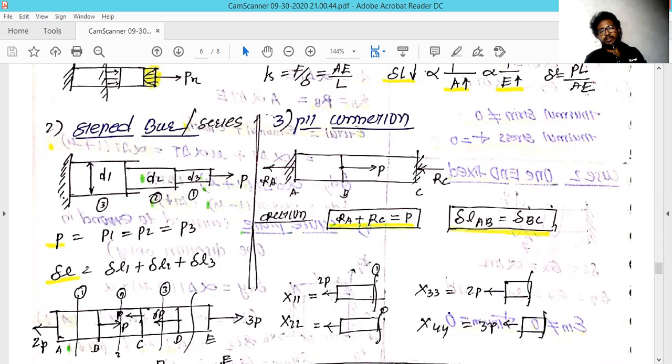So in this condition, the force in the three cross sections will remain the same, but due to the change in dimension, the area of these cross sections changes, because we have seen above that the area is very important, and the areas of these three cross sections are different. So more change in length is going to be produced in the smaller diameter, which means the smaller area.